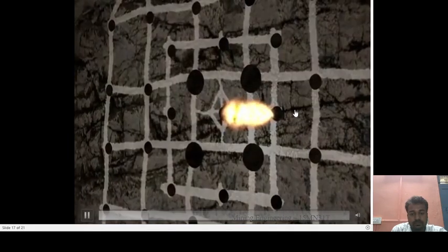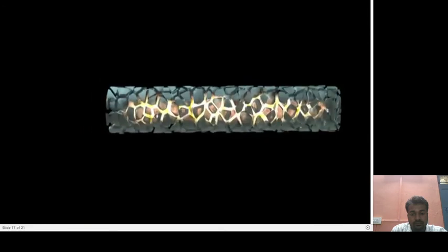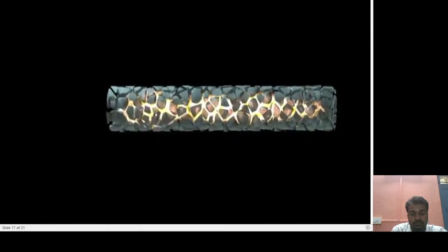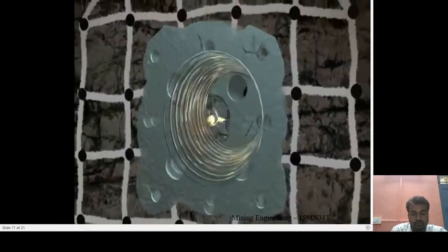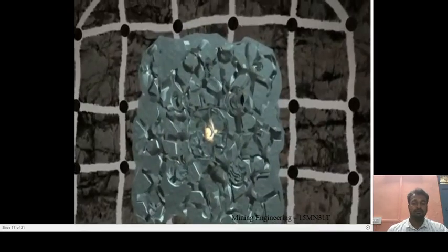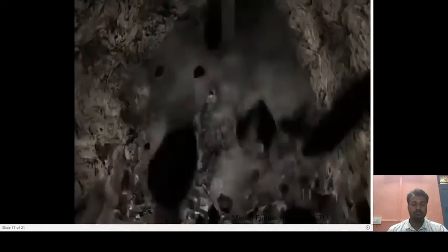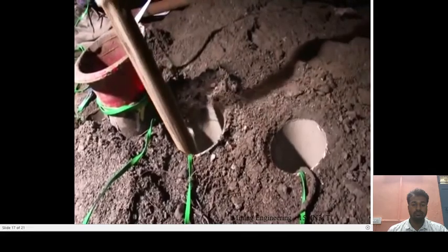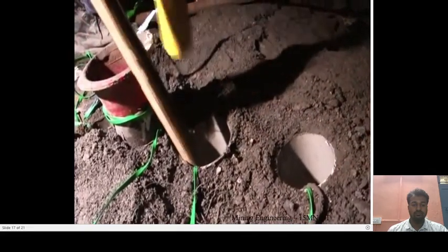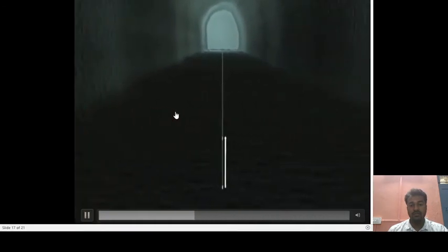The explosion exerts very high pressures, way above the rock strength. This creates a zone of crushed rock immediately around the hole. The explosion also generates a shock wave which starts the cracking process. The explosive gases generated expand extremely quickly, forcing cracks apart, breaking the rock and pushing it into the nearest void. Long holes may use multiple primers. They are typically placed at the toe of the blast hole and then at predefined intervals as determined by the drill and blast engineer. So the booster is being inserted along with the detonator. Enough primers are used to ensure that the long explosive column is initiated.